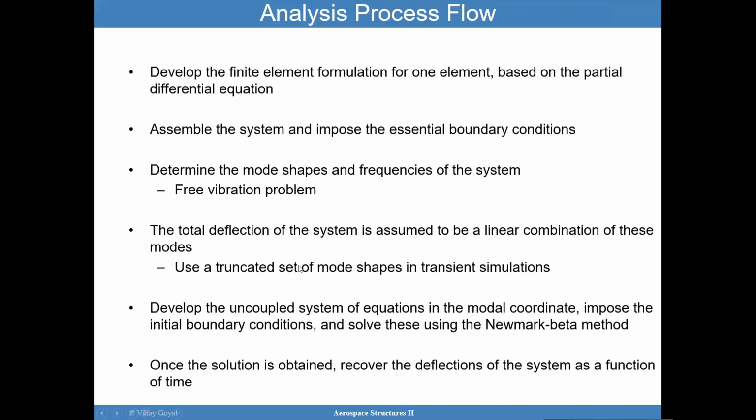How to determine the truncated set of modes? Say you have a forcing frequency of 50 hertz. You want to make sure that any natural frequencies, even past that, are included in your assessment. Let me backtrack again, I keep saying it incorrectly. I want to make sure it is clear to you that you have a forcing frequency and you know the frequency content of that. You want to truncate past that forcing frequency. You want to be able to account for that